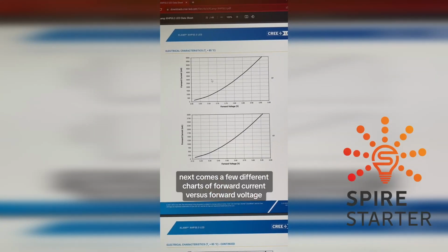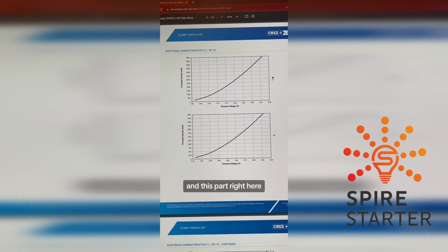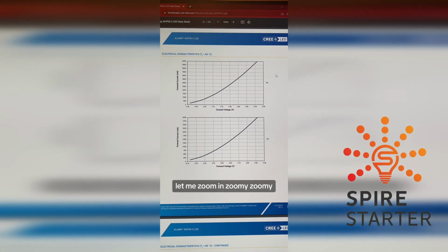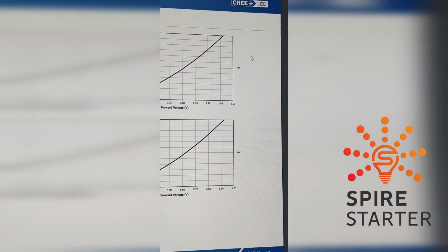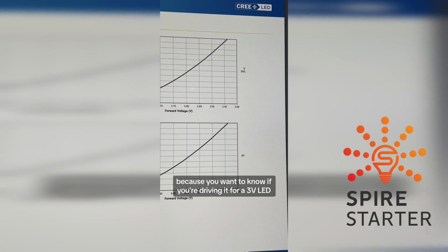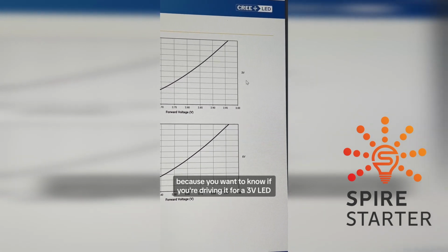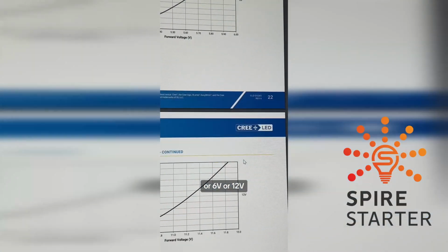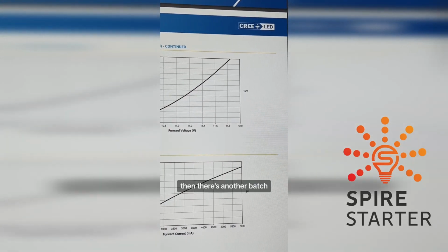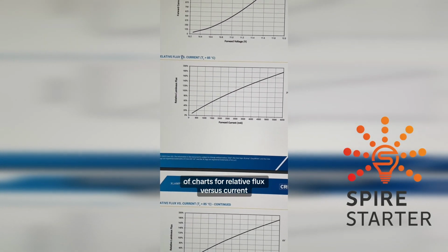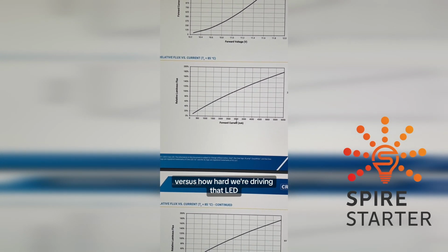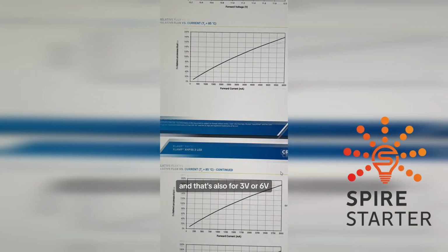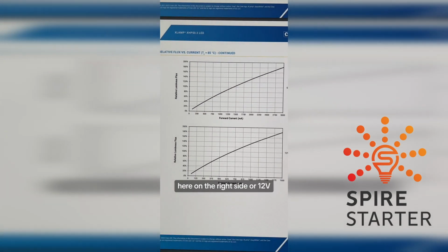Moving on. Next comes a few different charts of forward current versus forward voltage. And this part right here, let me zoom in. This part's really important because you want to know if you're driving it for a 3 volt LED or 6 volt or 12 volt. Then there's another batch of charts for relative flux versus current. So how much light we're getting out versus how hard we're driving that LED current-wise. And that's also for 3 volts or 6 volts here on the right side, or 12 volts.